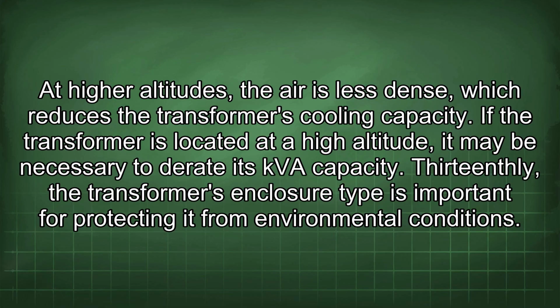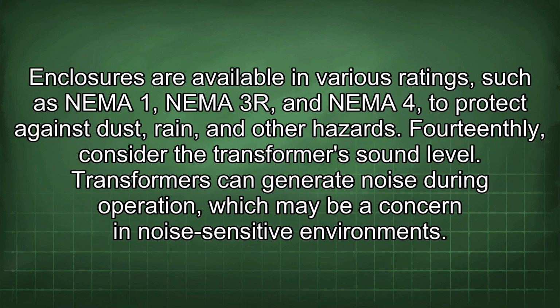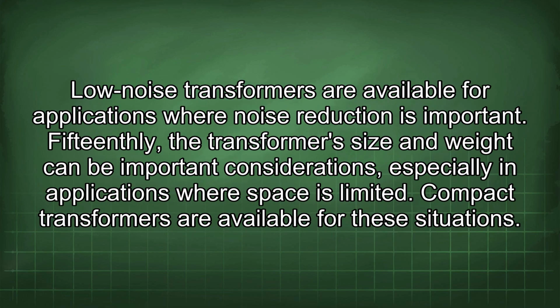Thirteenth, the transformer's enclosure type is important for protecting it from environmental conditions. Enclosures are available in various ratings such as NEMA 1, NEMA 3R, and NEMA 4 to protect against dust, rain, and other hazards. Fourteenth, consider the transformer's sound level. Transformers can generate noise during operation, which may be a concern in noise-sensitive environments. Low-noise transformers are available for applications where noise reduction is important.